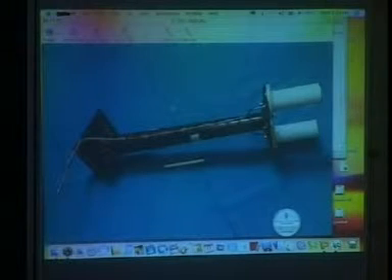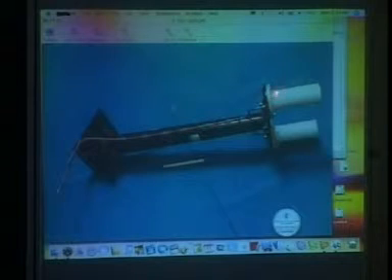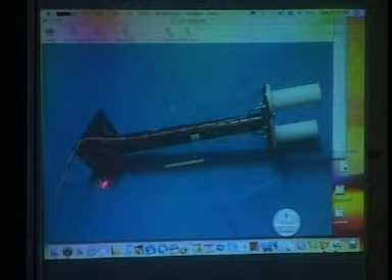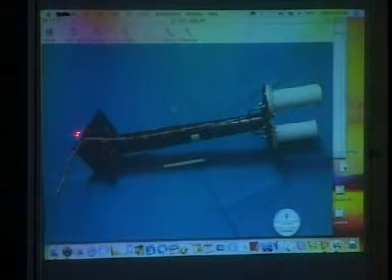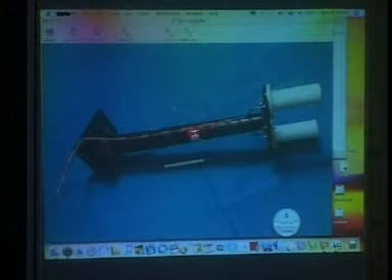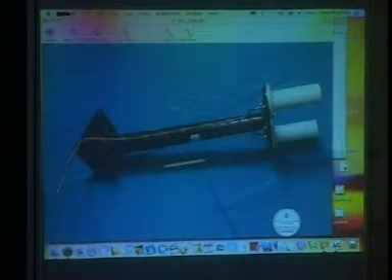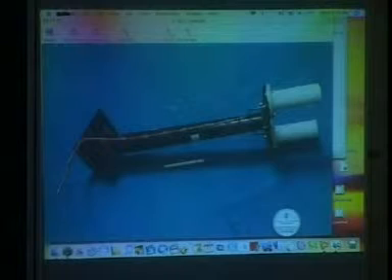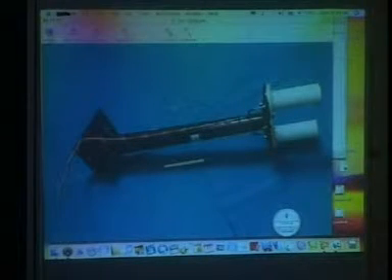After the antenna which we saw here, now they are fully assembled. This is the radome, and this is the connector, and then this is the mounting structure, the mounting boom, and this is directly fixed onto it. See how neatly the cables are coming out. This is actually a semi-rigid cable, because we wanted to reduce the loss, and in semi-rigid cables the loss is minimum. This is called 0.141 inch semi-rigid cable, and the connectors are also special crimped connectors where there are no solder joints.